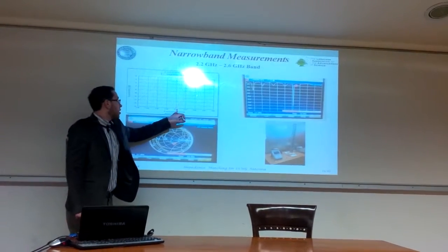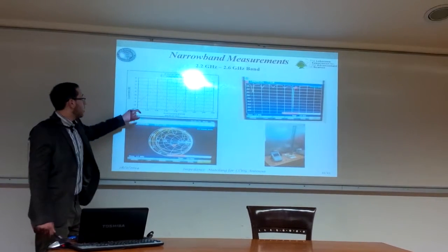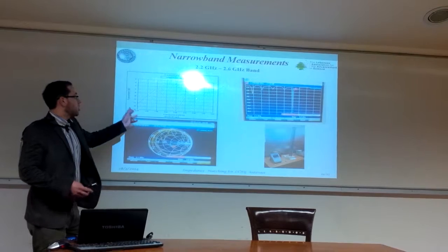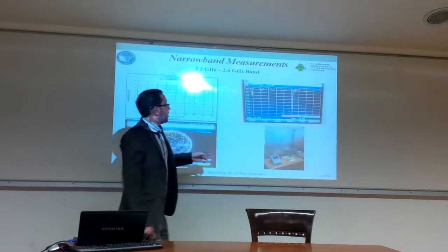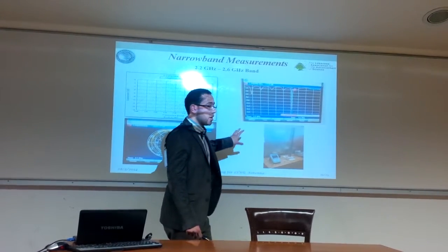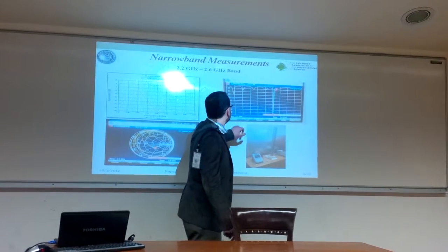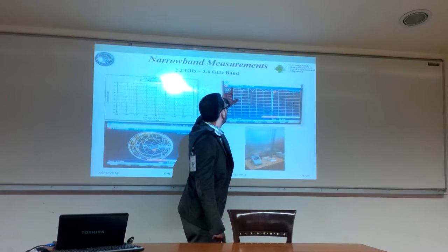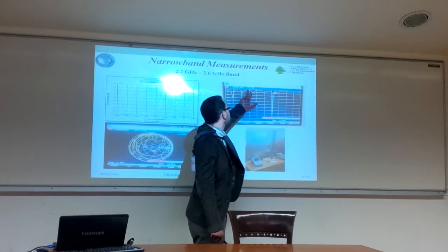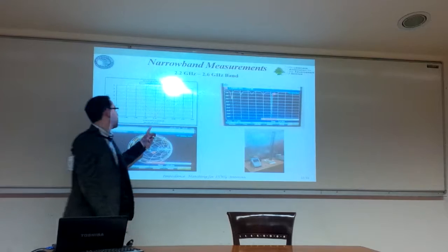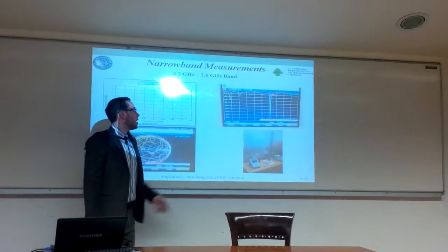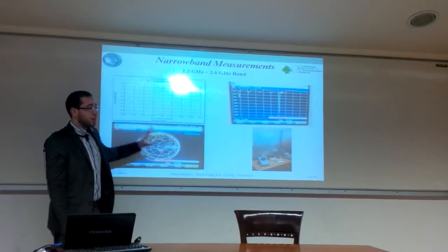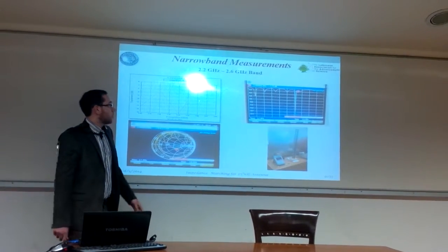So at 2.4 GHz, our desired frequency, we had minus 18 instead of minus 33 after taking the fabrication errors into consideration. And this is the graph from the vector network analyzer, and it's not very clear here. At 2.4 GHz, we had minus 17. So comparing the simulation results and the lab results, there is only a 1 dB difference. So the simulation reflected the real results.